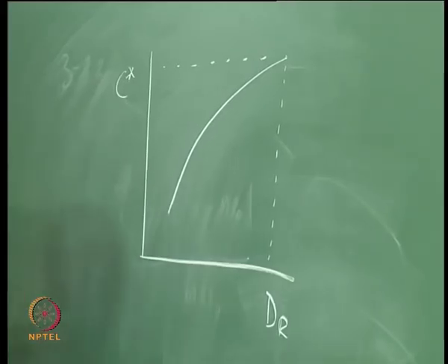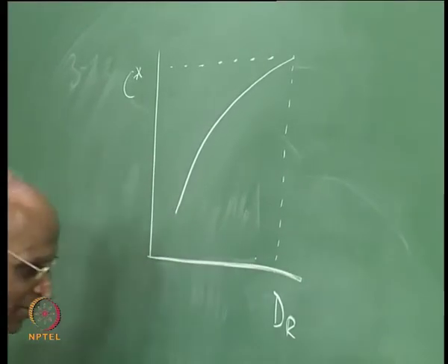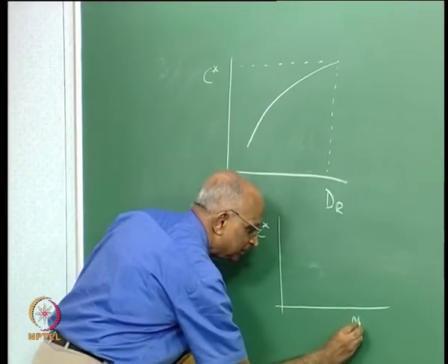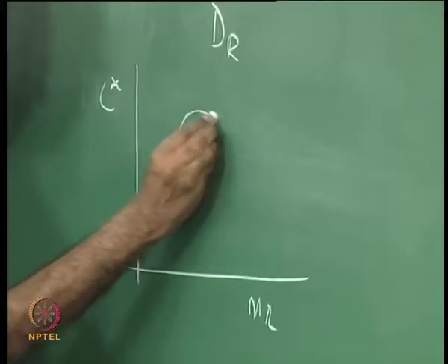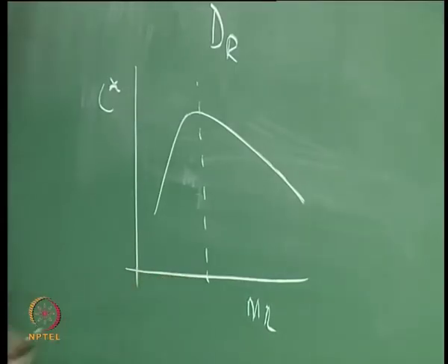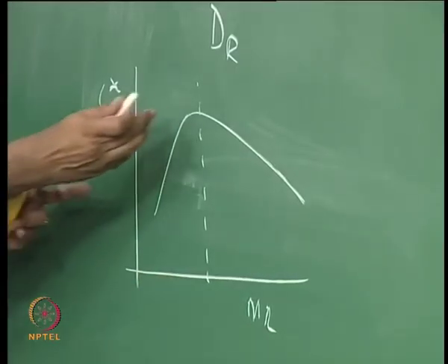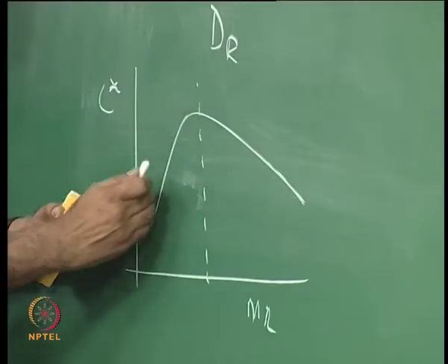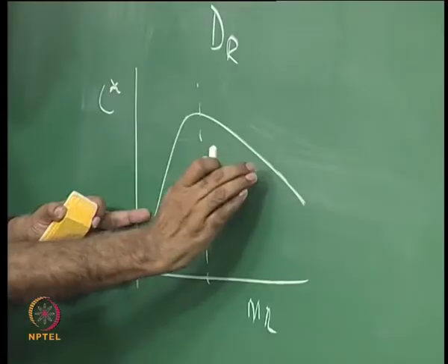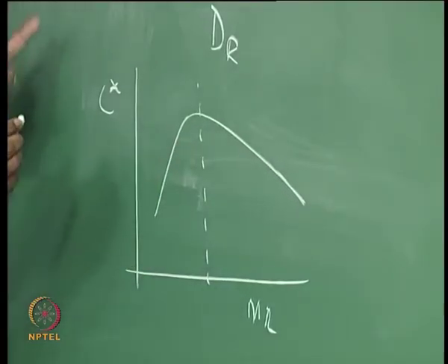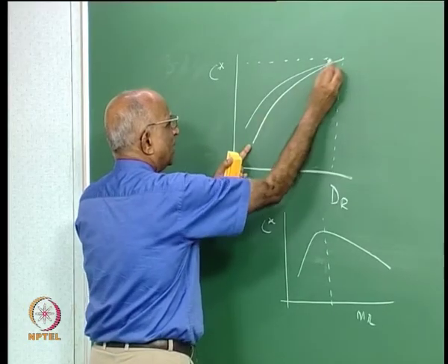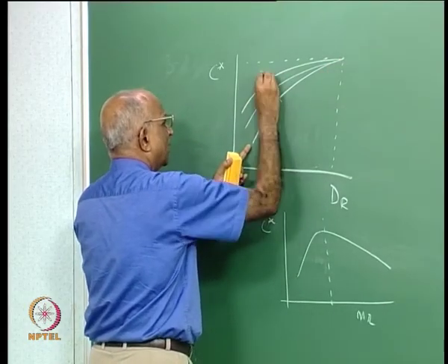But when we looked at this particular figure, which I keep erasing each time, and even though I have to use it, what was the shape like? It is like this. This is the nominal value of, let us say, MRO which I choose. I find that the slope of this in the fuel rich region is somewhat steeper, in the oxidizer rich region it is somewhat shallower, and therefore, if I increase the value of mixture ratio, I will get curves which go like this.